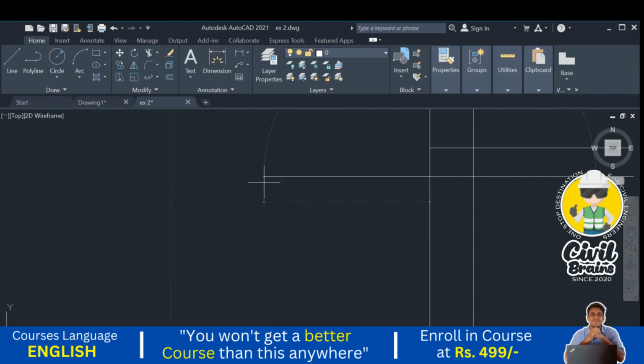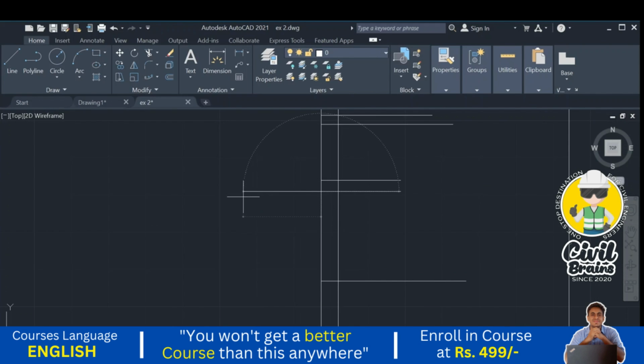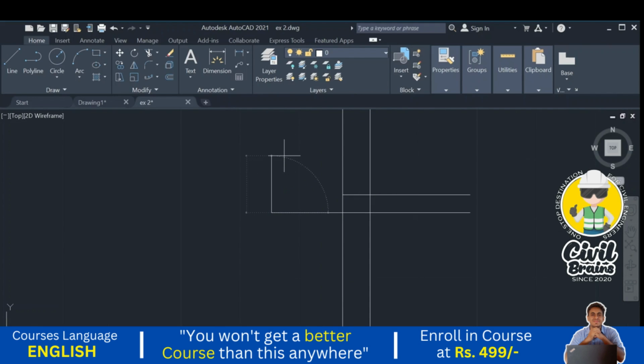And the projection of the chhajja also we need to show here, correct? What is the projection? Sorry, not projection of the lintel, projection of the chhajja. At the level of the lintel we need to provide that one. At the bottom of the lintel we need to provide the chhajja. The projection of the chhajja is 0.6 meters. I just press enter. What is the thickness?